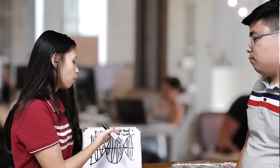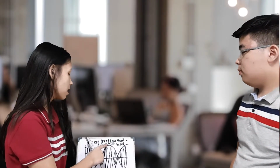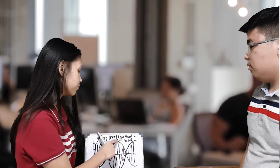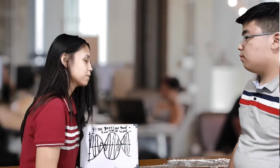Yes, I could. According to the data that you handed me beforehand, there's 450 Hertz and 455 Hertz. And when you substitute it to the formula, it will be cosine 900 pi t plus cosine 910 pi t equals 2 cosine 905 pi t and cosine pi t. This is the frequency, as you can see, which can be used for the task that you're giving me, and I will be able to use this in order to do so. You'll get it done soon.